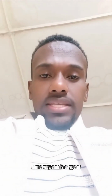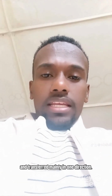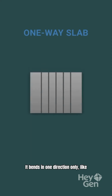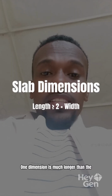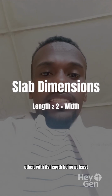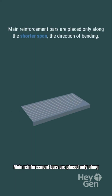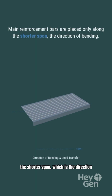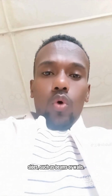A one-way slab is a type of RC slab where the load is carried and transferred mainly in one direction. It bends in one direction only, like a beam slab. One dimension is much longer than the other, with its length being at least twice its width. Main reinforcement bars are placed only along the shorter span, which is the direction of bending. The slab is supported by two opposite sides, such as beams or walls.